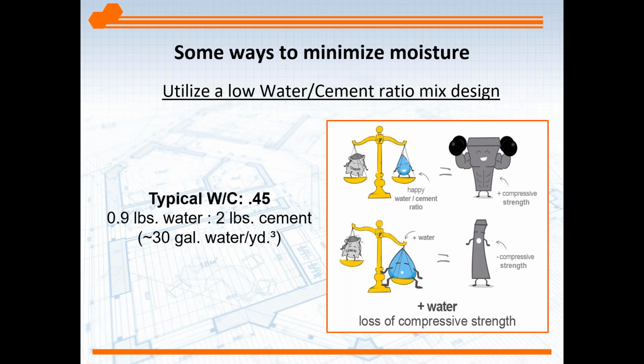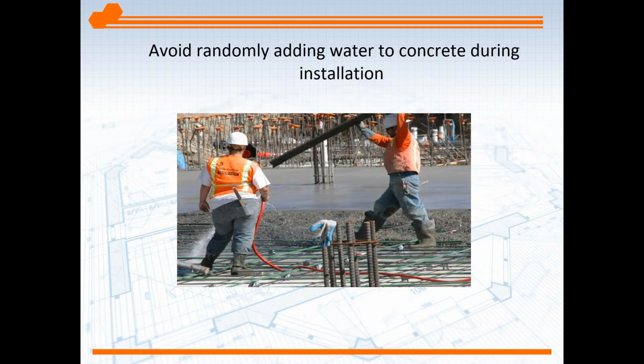And too much water, again, might seem like a benefit. It makes the concrete easier to install because it's much more fluid or flowable, but you lose strength and you lose durability at the surface if that water cement ratio is not followed or is ignored in the field by adding water to the concrete. So the water cement ratio is taken care of by the specifier, and it's generally in this range.